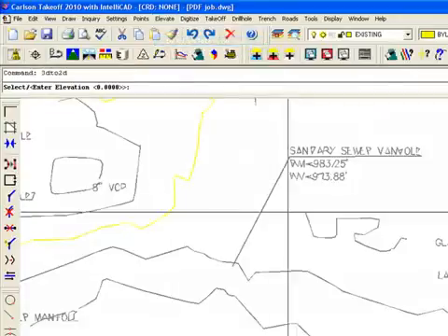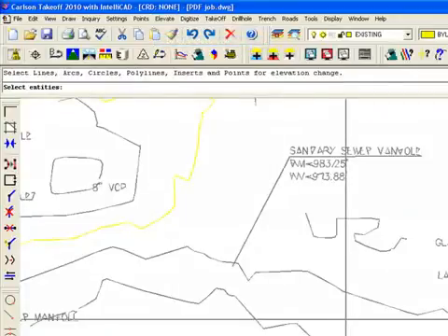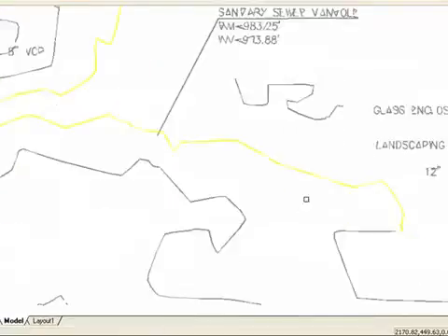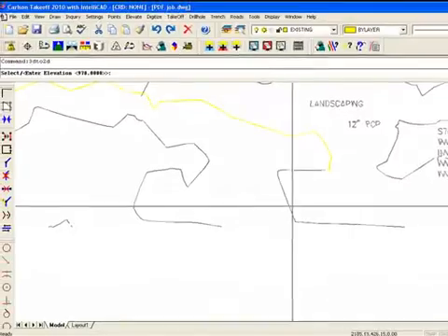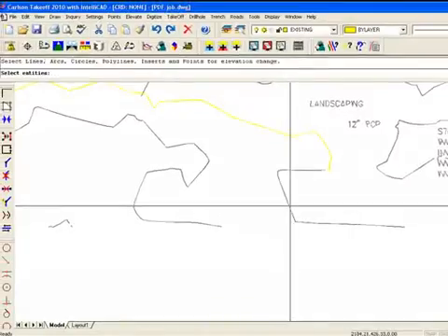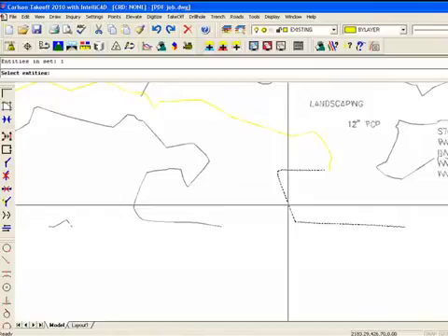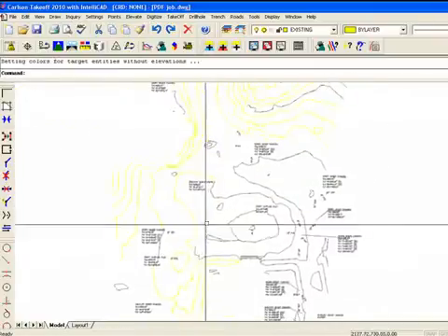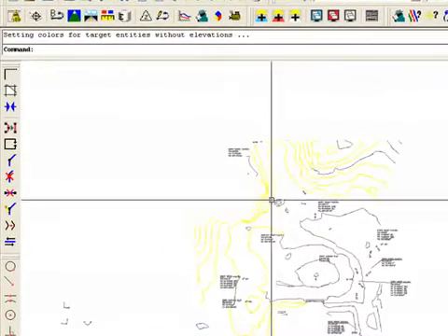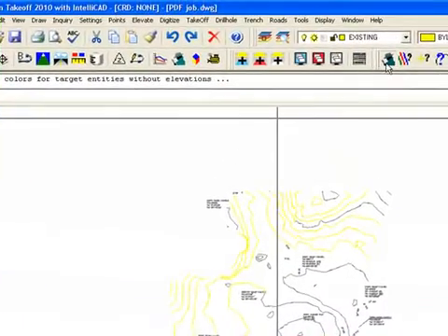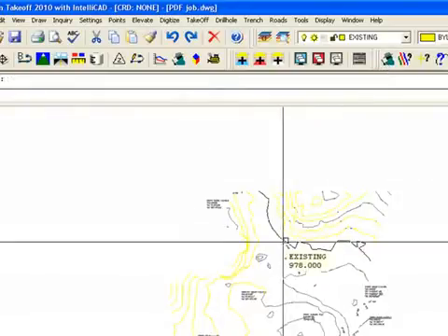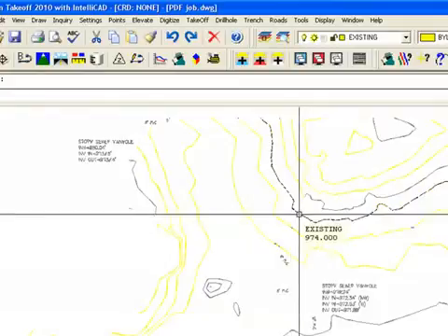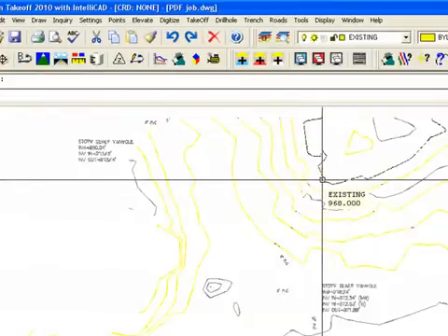Elevate, set polyline to elevation 978, and I'll click on this polyline, press enter, change one, enter again, enter for 978, and I want to change that elevation as well. Okay, I could go through and do that on this whole drawing, and once I did that, you can see this now has elevation 978. They're in 2 foot intervals, 976, 974, 972, going on down.